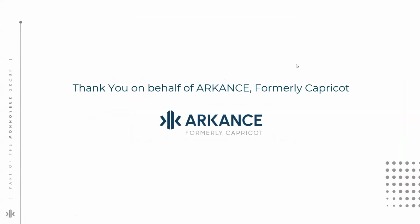So from Mohit, it was one of the questions. Can we use the Revit model directly to do energy and daylight analysis? Yes, you can, but it is not inbuilt within the platform. For this, you need to go on to manage.autodesk.com, and then you can install those particular plugins from there, which will get directly incorporated with the interface of Revit, I would say.